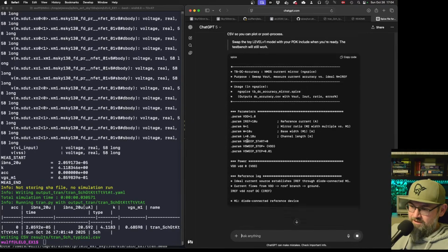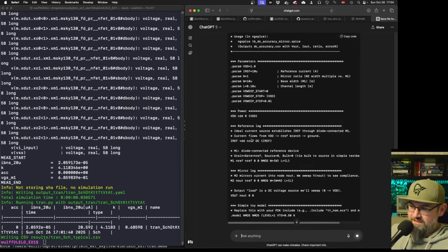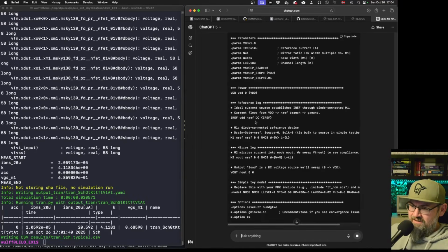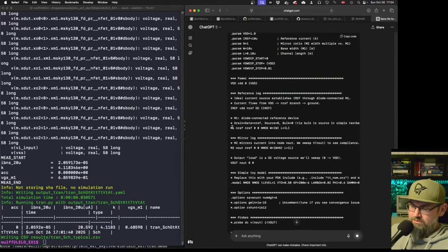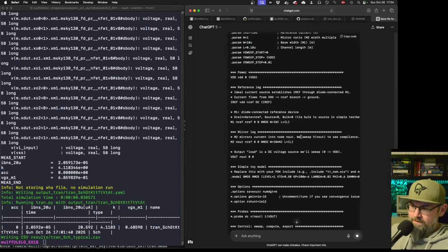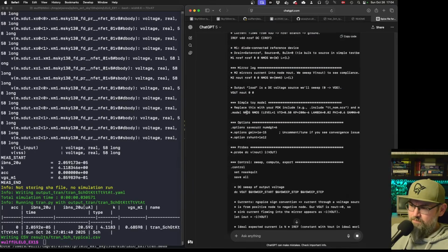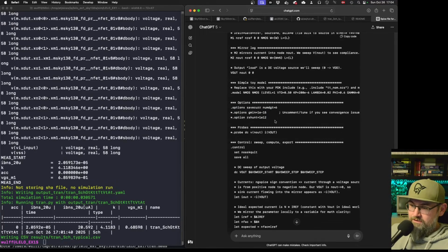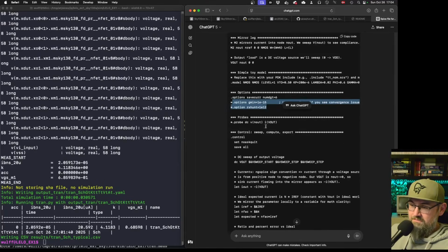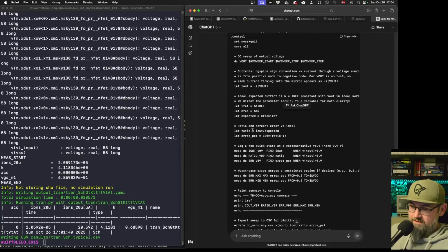Params, okay, we can VDD, yeah. IRF, okay. Now this you'd replace with the actual design. The model you don't need. Wow, it even has Gmin for convergence issues. That's really good. That's impressive. And then the different simulations.